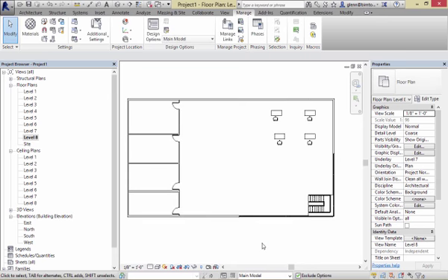Say close to that. So we're now looking at what's considered the main model. The main model down here, that is the default. It's the constant that we're looking at. And for the issue of the wall layouts, there's a few things I'd like to make changeable. So I'm going to leave the stairs and the outer boundary all just the same. But these interior walls right here, I'm going to say that's something I might want to change between those two different options. So how I do that is, by default, everything's in the main model.